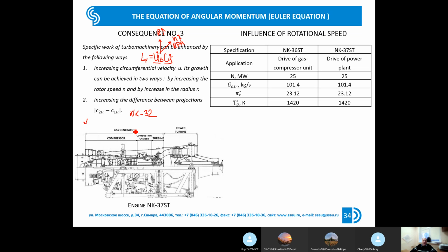But approximately 30 years ago, this engine was modified and converted to the ground application. So the bypass was closed, the low pressure compressor was modified, the last stage of the low pressure turbine was removed, and of course the elements which are not used in the ground power unit were removed. The mixer, the afterburner and nozzle were removed.